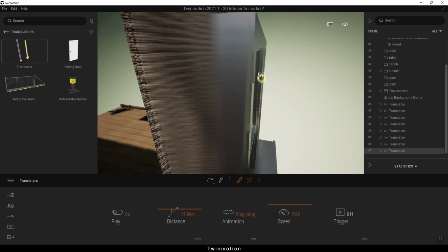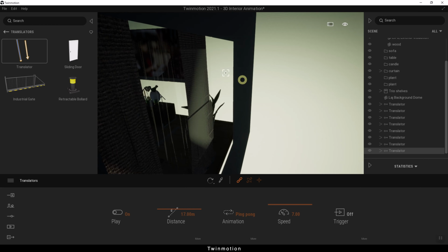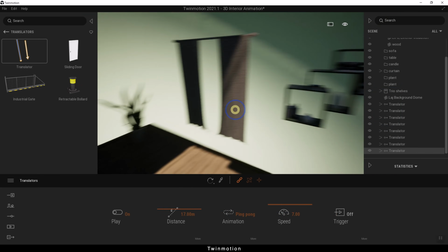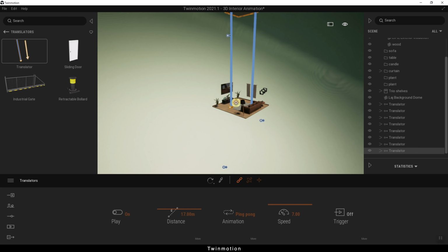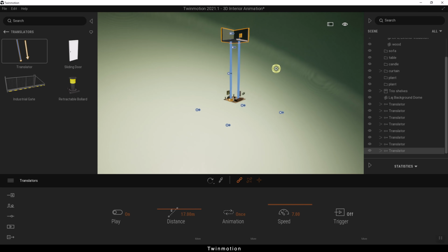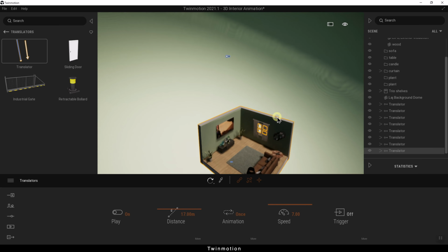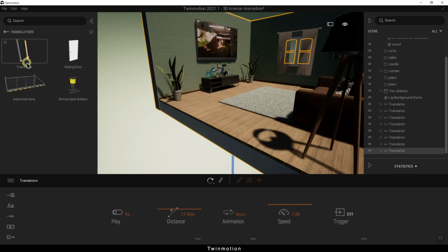I should have linked the window to it too, so I will come here and link the window to it from this side as well. Now it's okay, I also link the window and the middle glass to it. The point is I have to set this on once, right? I put it on once. It comes up from the bottom. Now I set this to 17 meters. I click, I command it to come down minus 17 meters. Look, I am on its gizmo, minus 17 meters, it came exactly here.